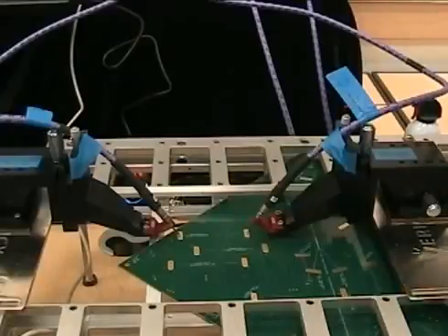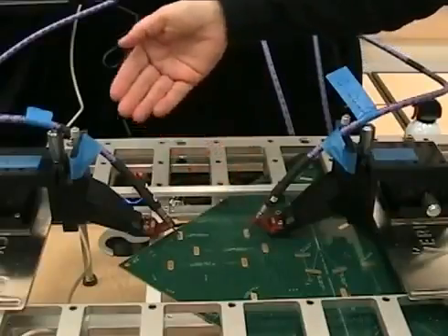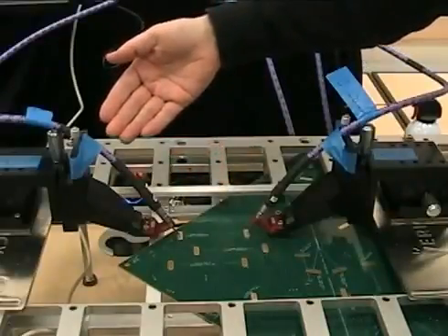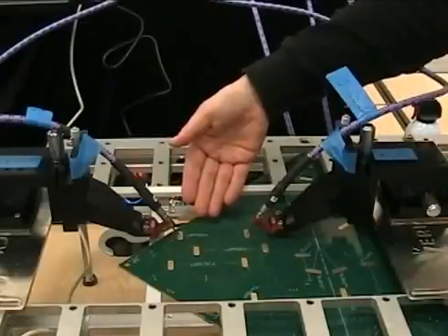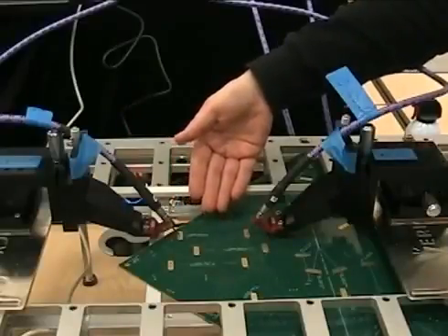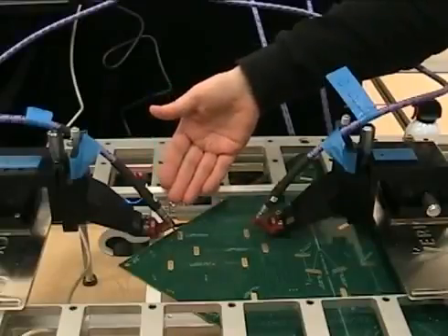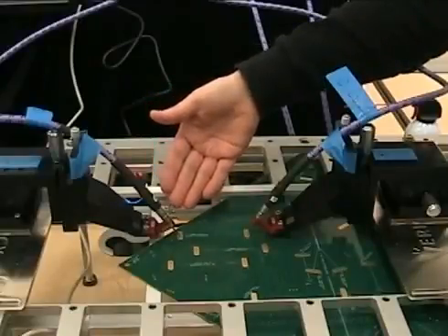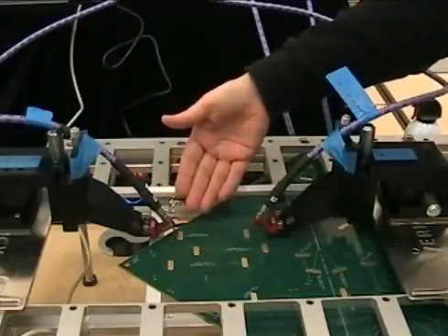Taking a closer look at our printed circuit board device under test application, we see that we need to make a connection with our coaxial cables from the network analyzer to the planar surface of the printed circuit board and onto the transmission line. We could use a connector, but in this case, our small ground signal ground coaxial probes provide a consistent, high-performance connection to the printed circuit board.